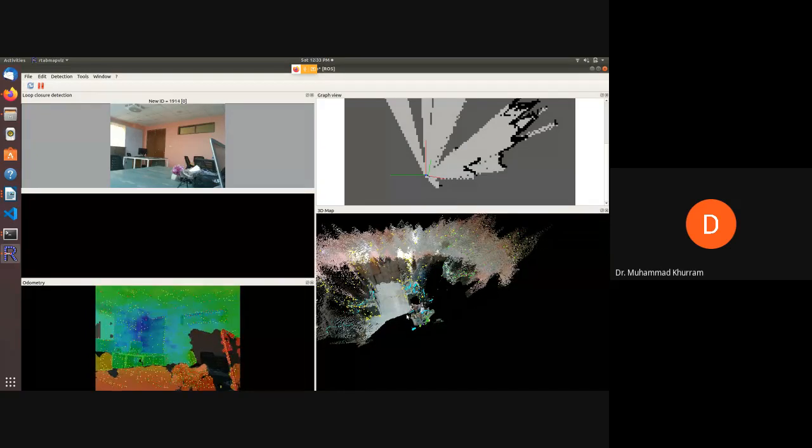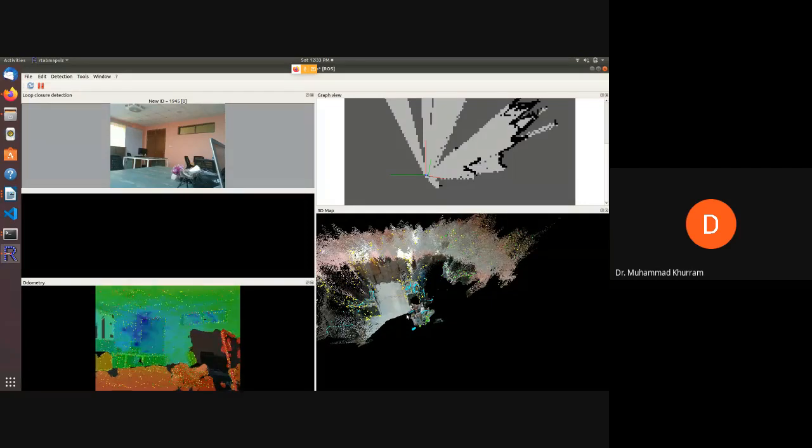So then after the filtered data comes the perception module, using the raw information from the environment. The mapping modules create different levels of maps: the 3D maps, the 2D maps, the road maps, the HD maps, online maps, offline maps. It makes many different maps, uses a conjunction of those maps, and passes these values further. This is the perception module. It passes these values to the motion planning module.